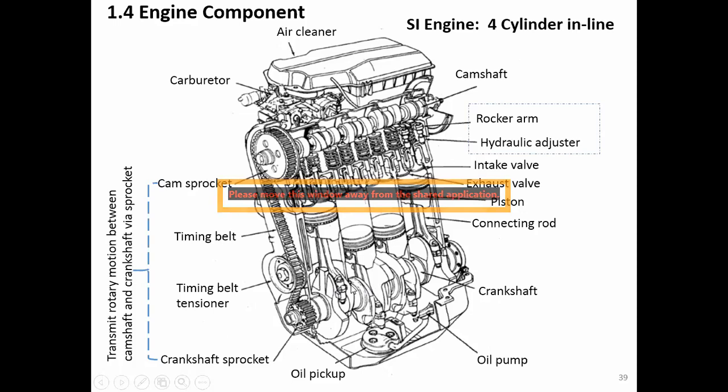So the crankshaft will send the timing to the crankshaft sprocket, to the timing belt. The timing belt can always keep the timing because of the tensioner here, and then it will send the timing to the camshaft here. The camshaft, after receiving the command, forces the cylinder to work according to the timing that the crankshaft provides here.